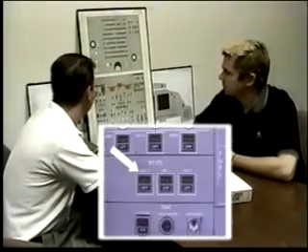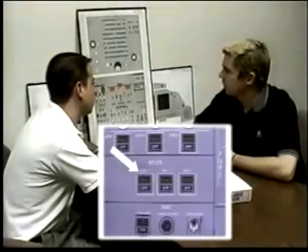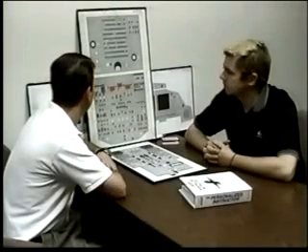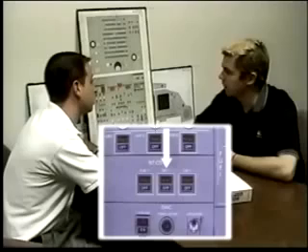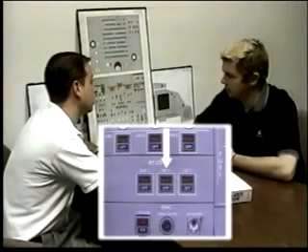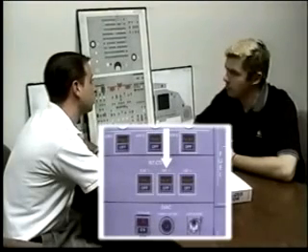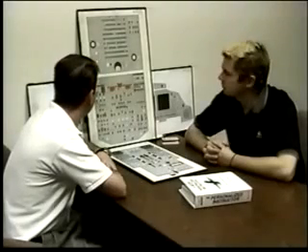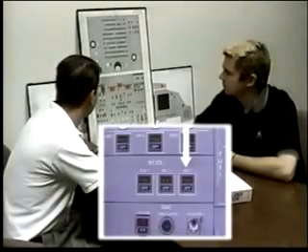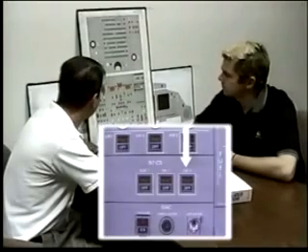Let's say ELAC 1 fails. What would occur now? ELAC 2 would back it up. What if both ELACs should fail? If both ELACs fail, the SECs will back them up. But in the roll, it can't back up the ailerons. It can only do the spoilers. FACs. Flight augmentation computers. You described to me the 3 things that the FACs do.